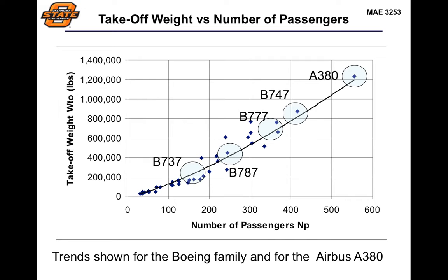Again, that's based upon the fact that you have a lot of these operating requirements coming in and being driven by various use cases by the customer. Now, something more direct physics is taking the number of passengers with the overall takeoff weight. Passengers are payload, so as we scale the payload up, we expect the takeoff weight of the aircraft to scale as well.